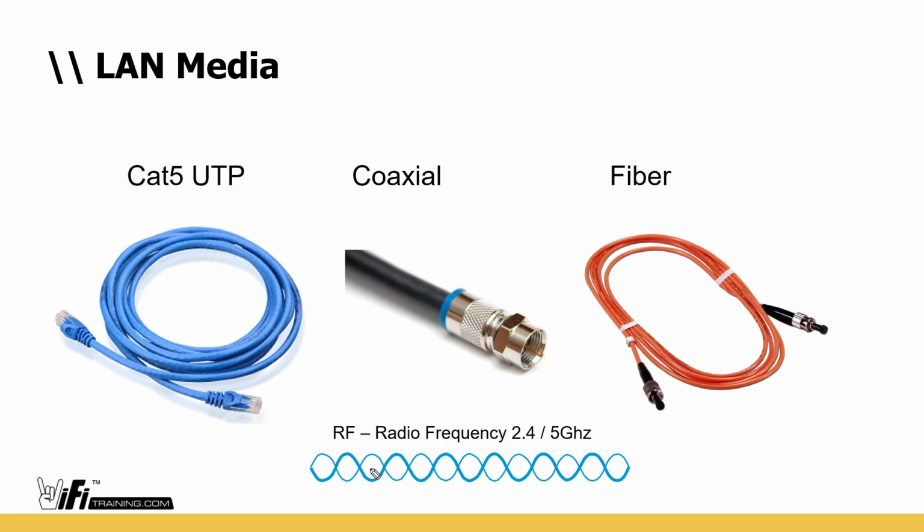So the predominant media we use is a specific channel, okay? And we have certain channels that are allotted that we can use, or certain bands, radio bands that we can use, and the 2.4 gigahertz industrial, scientific, and medical bands in the US. And we also have some 5 gigahertz industrial, scientific, and medical channels. And then we have a lot more 5 gigahertz channels that are allocated to us in what's called the UNII bands, which are the unlicensed national information infrastructure bands.